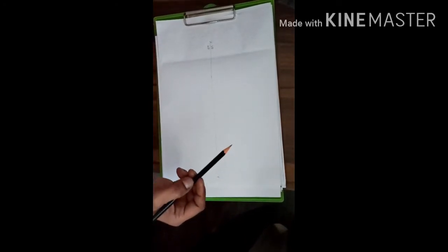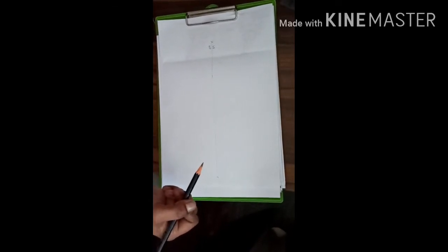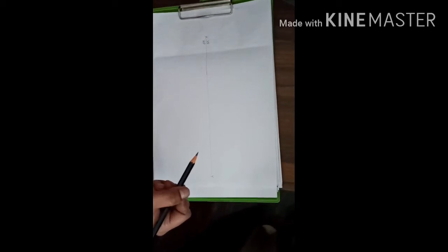A square pyramid of base side 45 mm, with all the base sides equally inclined. To satisfy this condition, first we should take a small reference line, put a point here and draw the top view of the square pyramid, which is of 45 mm sides.